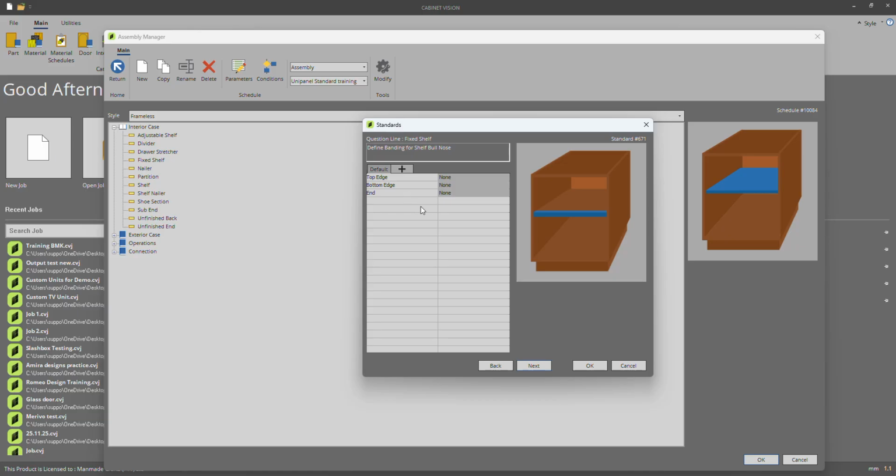So what DJ is saying for fixed shelf, you limit it to edging just on the side. Because it's fixed, it knows you're connecting it on the other side. The problem is if you add edging onto the sides of that fixed shelf, because there's connections there, that edging is going to push the part away from the side, so that machining's not going to fight. It's going to gray out the connections like I showed you guys. It does take the thickness of the edging into account, but the part itself needs to connect to that part. It doesn't recognize the edging and won't machine through the edging.